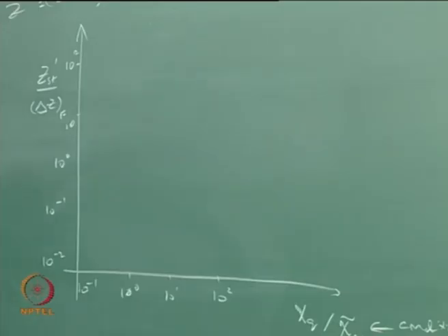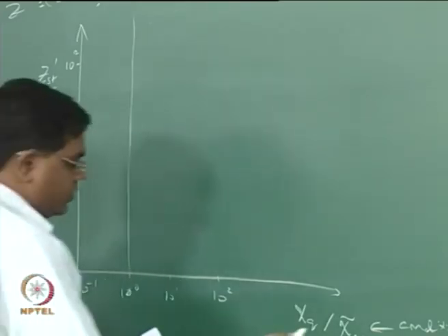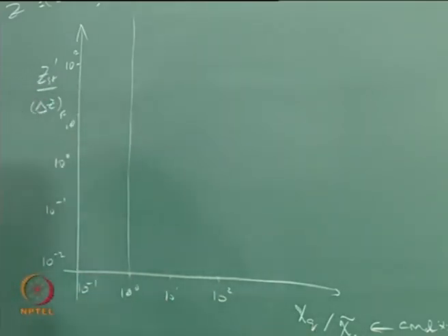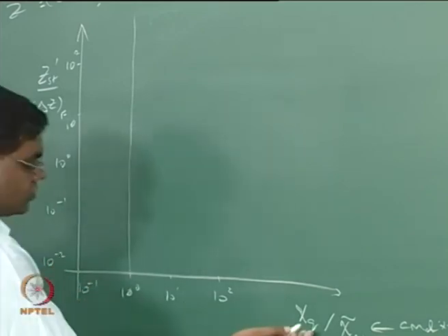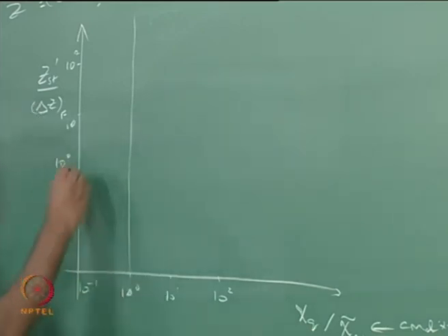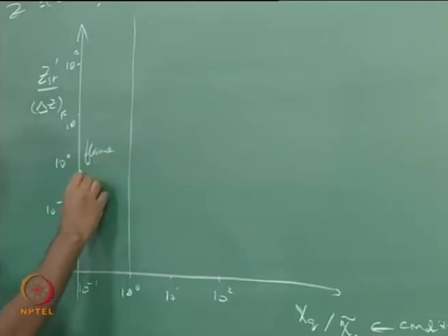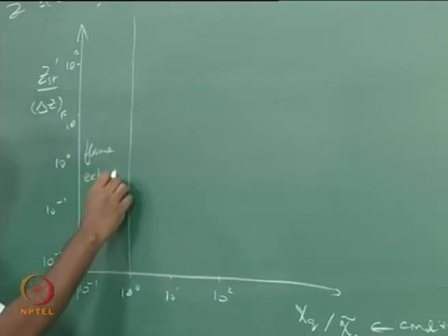And what we should be interested in is a region that's greater than chi q by chi st greater than 1, because when you have a region that is less than 1, this is the extinction chi. So essentially this corresponds to flame extinction, right?